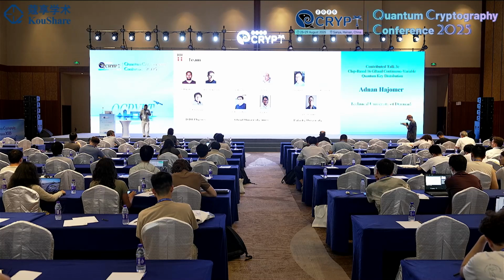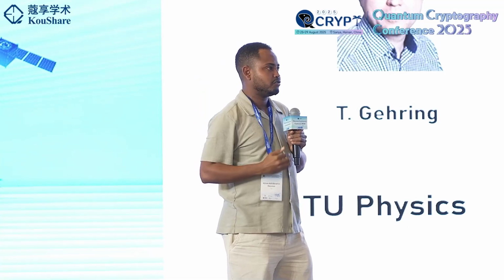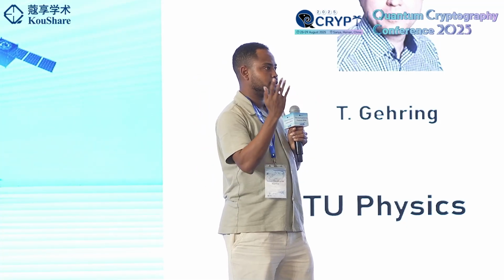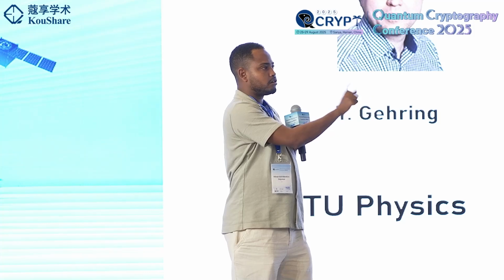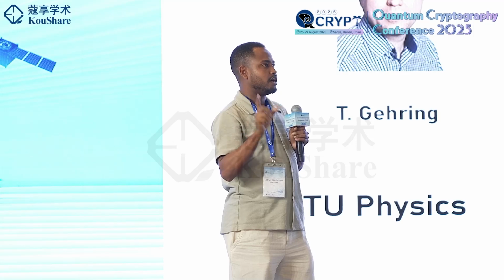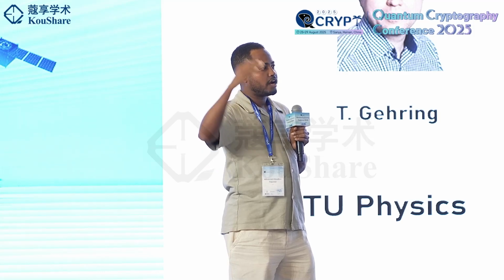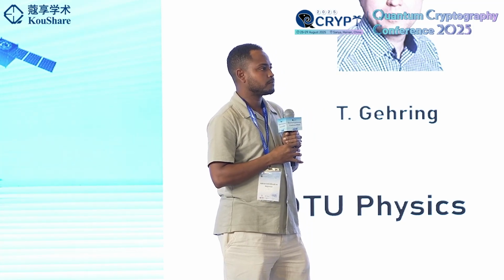This is a great question, and I can answer it from a different perspective. First of all, what is the limiting factor for the speed? Why not go to 20 gigahertz or 30 gigahertz for CVQKD, since, as I said, it is compatible with classical telecom? The limiting factor is not the transmitter side. You are right, we can use standard off-the-shelf IQ modulators from telecom, but it's the receiver side. It is very hard to get receivers with very high bandwidth that can still provide shot-noise-limited performance. So these are the limiting factors for CVQKD. But you are right, we can also go for a commercial system.